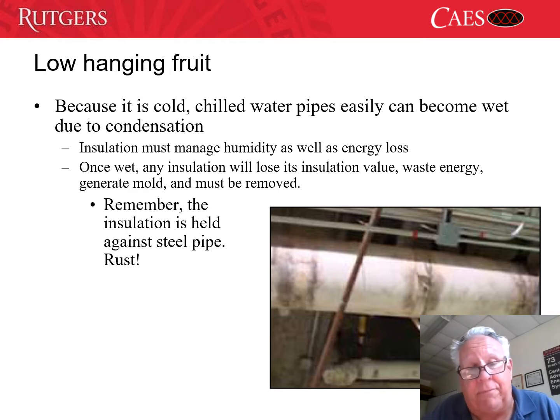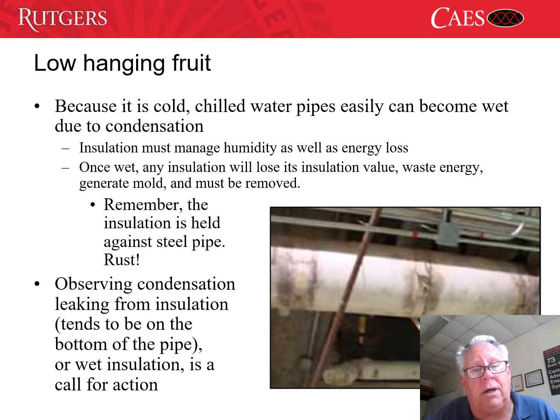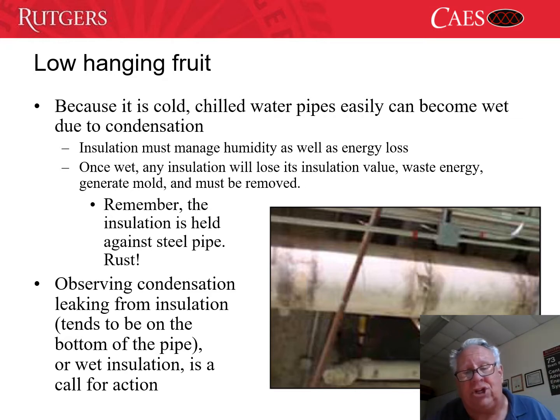And you also have, because these are steel pipes, you're going to have rust. So one of the things you do on an assessment as you go around is you observe for any kind of leaking, any kind of water. You can actually feel it at the bottom because of gravity of pipes. And so as you walk along, you just put your hand up there and see if there's anything, any water being held by the insulation.